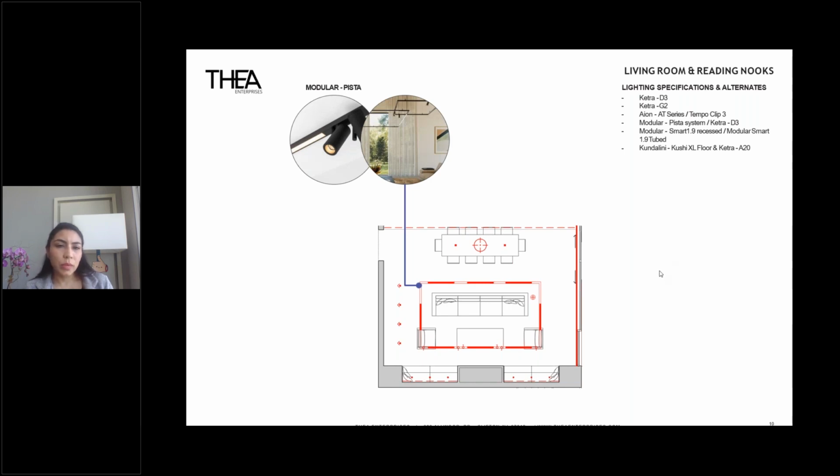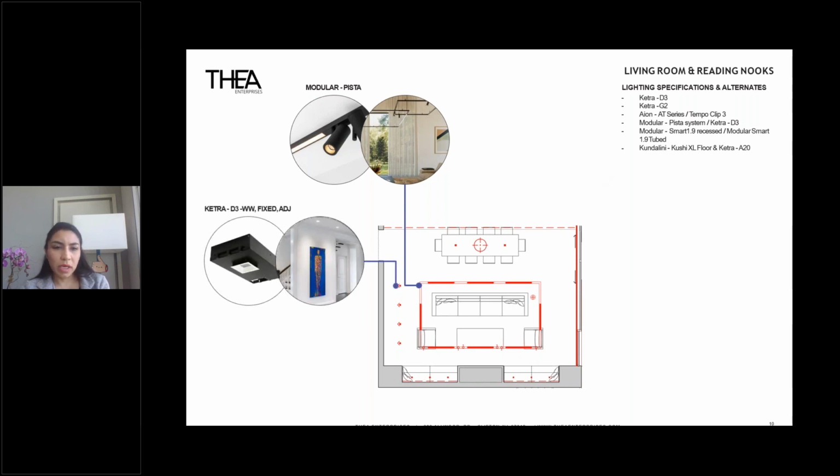As mentioned before, we were assuming a recess mounted fixture, but this can also be suspended or surface mounted, as you see here in these two images. And it can come in different finishes. So if the architecture is mainly white and you don't want to have any contrast, you would specify the white finish, but it also has some different accents. So as you can see here, it has a gold reflector. So it brings a little bit of decorative flair. If you have a high ceiling and you wanted to suspend this fixture, you could also integrate an uplight to have another layer of illumination.